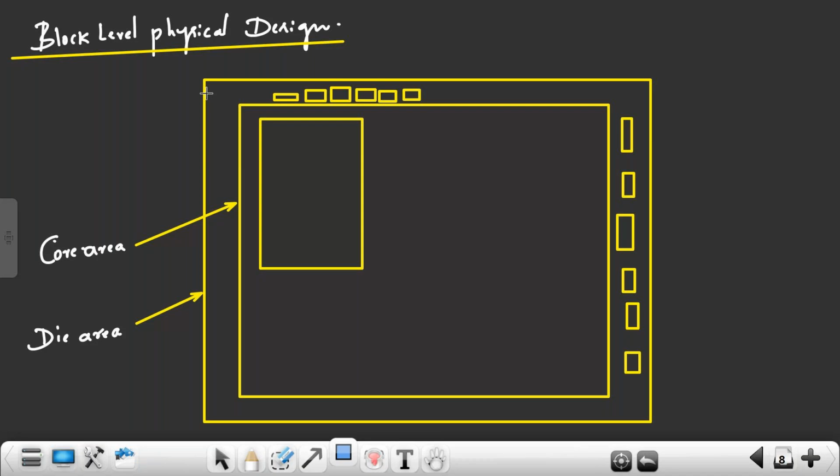And the second thing, some of the analog blocks, where we cannot write the Verilog code and do synthesis. There are a few analog blocks which we have to use. For analog designs, we cannot write Verilog code. We can write Verilog code only for digital design. Please remember, digital design means the signal has only two values, logic 0 and logic 1. Only those types of circuits can be written in Verilog. We cannot write Verilog code for analog designs.